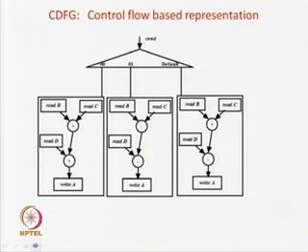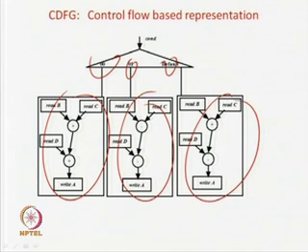So, next one is actually control flow and data flow based stuff. Already we have discussed in the last lecture. Based on some conditions, you either go for this computation, or you go for this computation. So, this is a control flow based representation. Given a Verilog code, it can be a hardware definition language, it can be directly transformed to this one and you are going to get your solution. Okay. So this CDFG can be directly obtained from your Verilog code. Okay, that is actually control flow based.